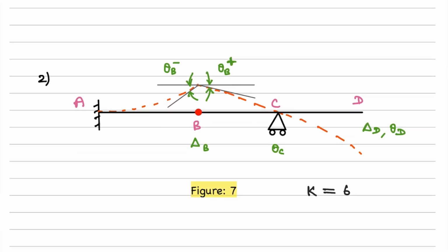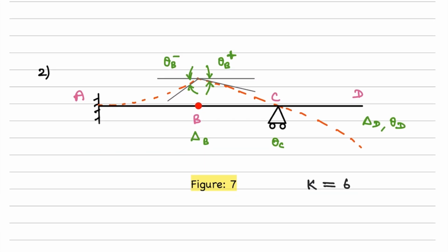In this second problem, we have what we call hinges or moment releases here. The important point about a release is that whenever we introduce a release at a particular joint or a particular location in a member, it is going to make the kinematic quantity corresponding to the release double valued. What do I mean by that?